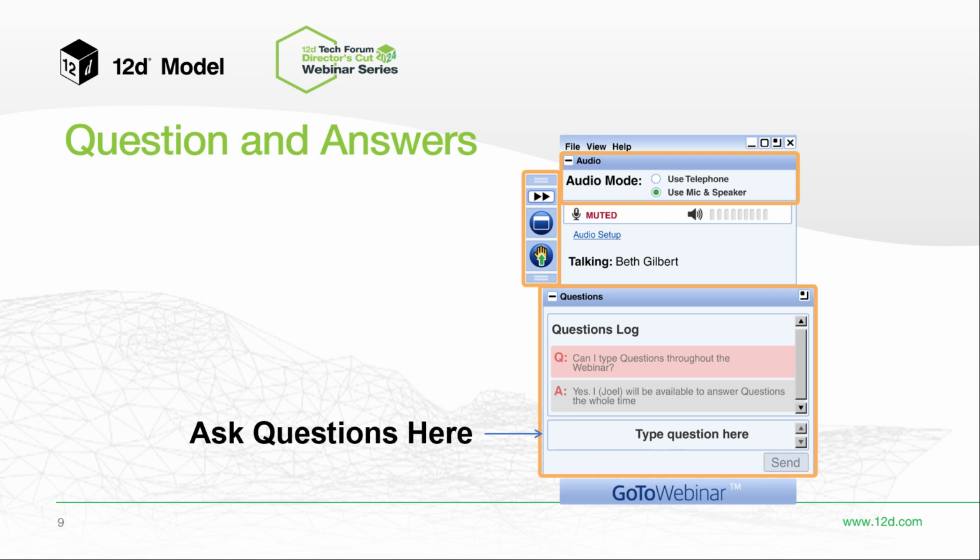So Andrew was asking, can you edit the markup rectangles and squares? Oh yeah, they are literally superstrings or normal 12D strings with vertices. So if you wanted to change the shape, you absolutely could. And because the attributes are just on those superstrings or trimeshes, you could make them look however you like, and then just carry through the normal status gateways.